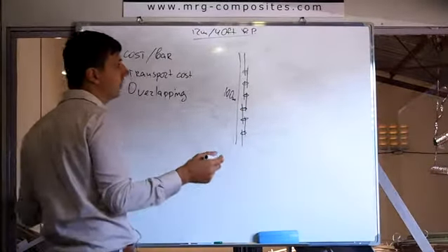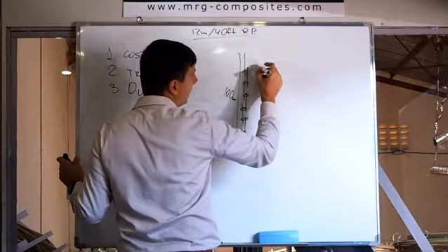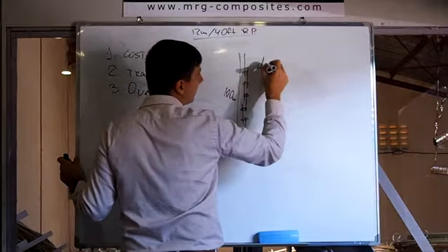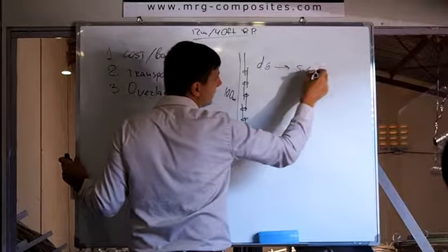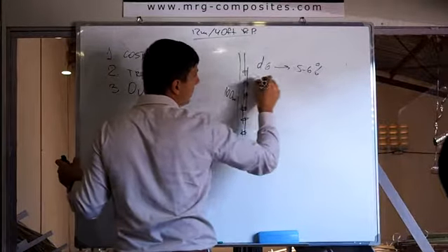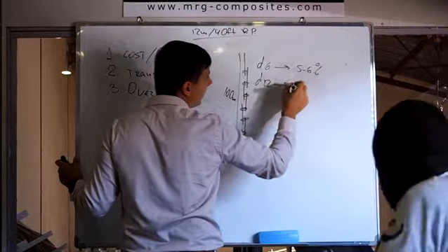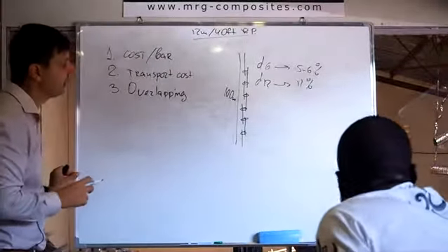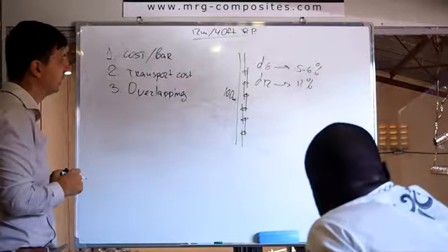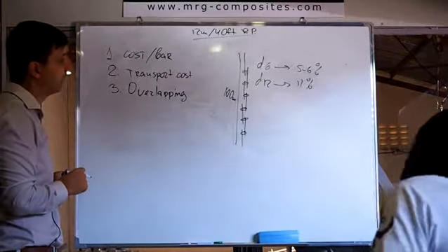One more time, I want to repeat that wasting, if you use D6 here, wasting can come up to 5-6%. If we use D12, wasting can reach up to 11% of your material. Just wasting for overlapping and all the things like this. So this is an important thing.